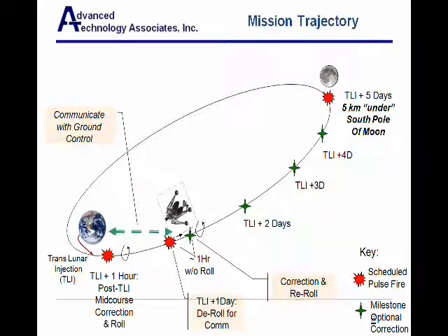This analysis resulted in the selection of 3 different points along the trajectory where we could make optimal use of the solid propellant on board. We had to use a spacecraft rotational barbecue mode to control the thermal environment of the vehicle during the 5-day transfer to the Moon. The mission plan stops the rotation briefly at the 3 mid-course correction points, thereby providing a window of communication for updates and corrections.